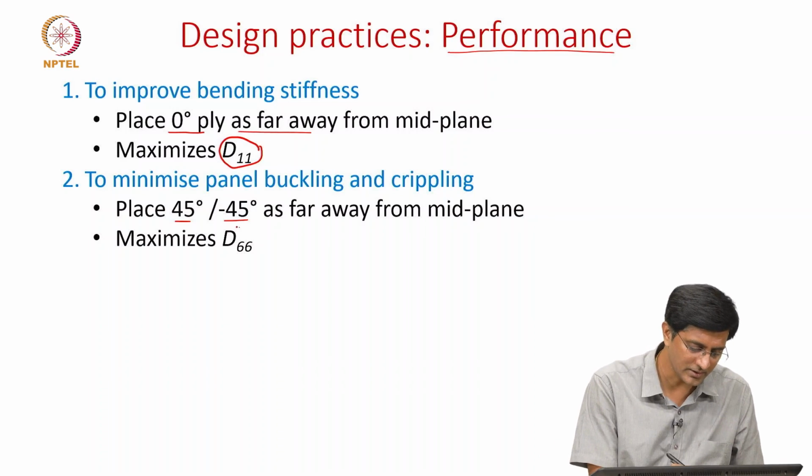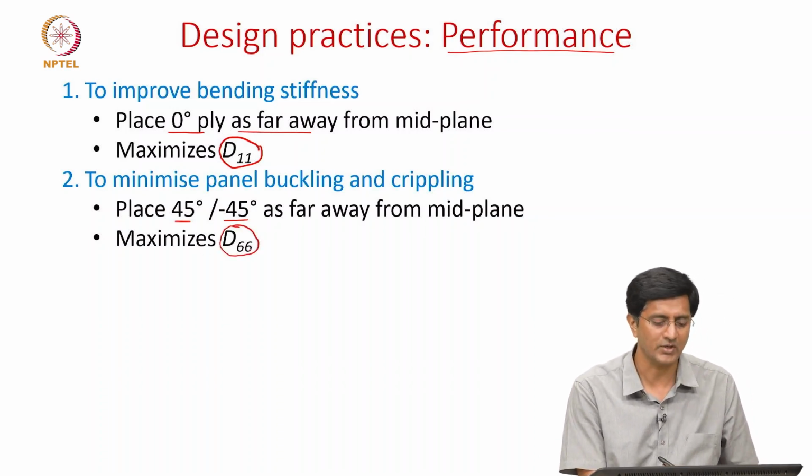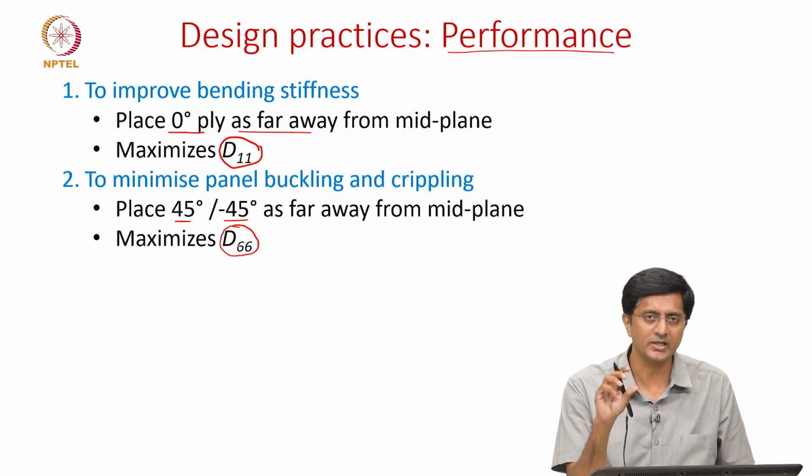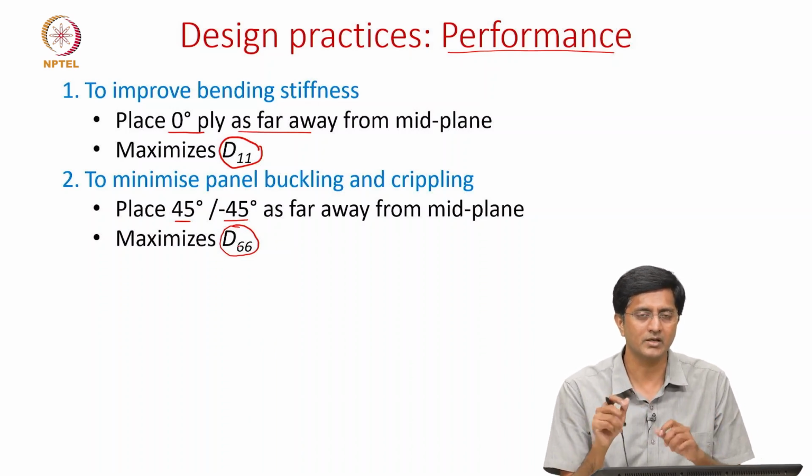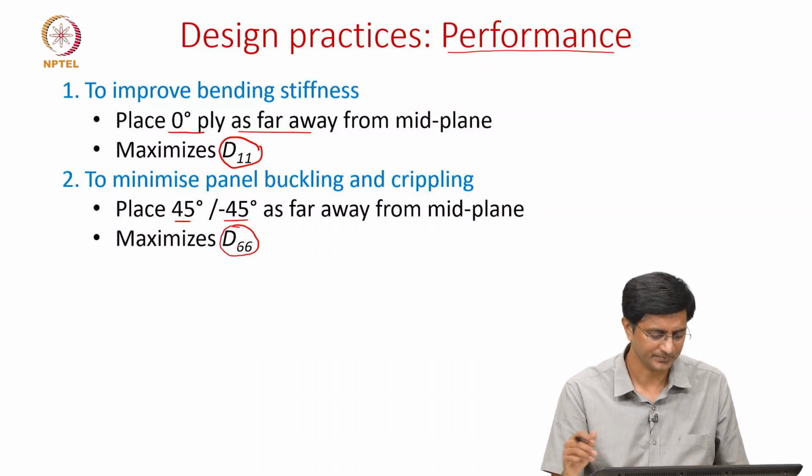What it does is essentially it increases your D66 values. D66 values, as you recall, are in the bending stiffness matrix, taking care mostly of the bending twist couplings.